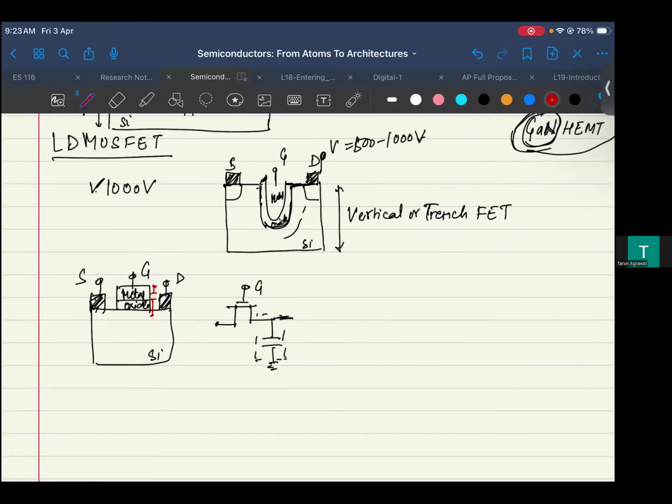Here what happens is, as soon as the gate voltage goes off, you see that there is no existence of the capacitor, right? Because the channel is not there, and that is basically as good as there is nothing happening there. So now the question is, is there a way that I can still store information by changing something in the structure? And that is the evolution we see: rather than this traditional structure or stack, we modify the stack. So we keep the oxide, which is your traditional oxide, but instead of that, we have this very interesting dielectric which we introduced, and then there is metal.